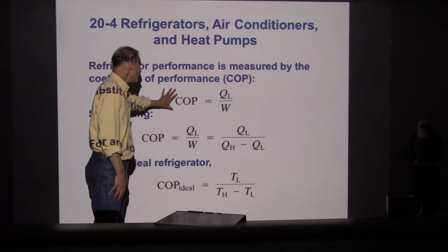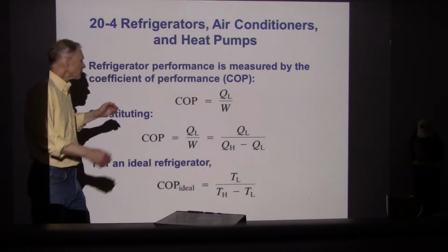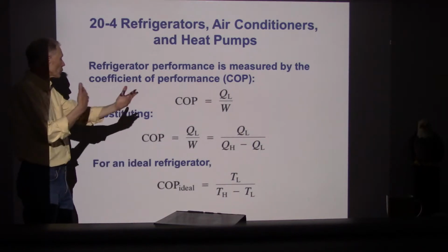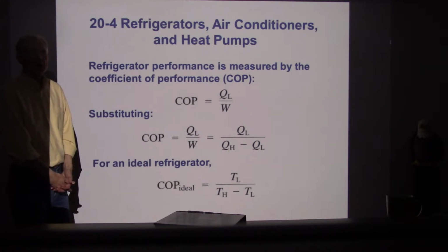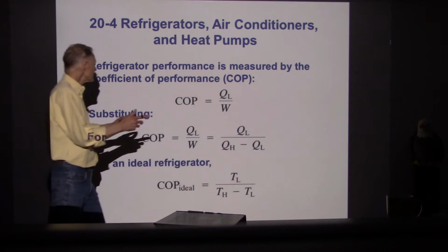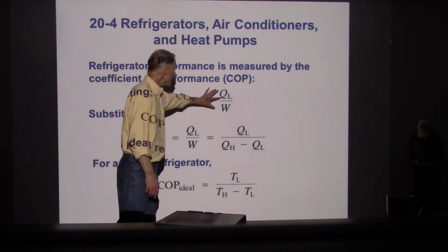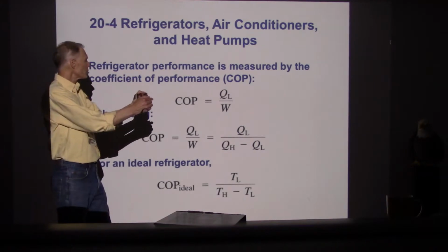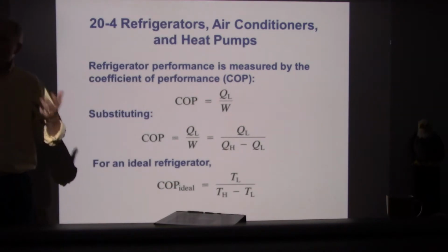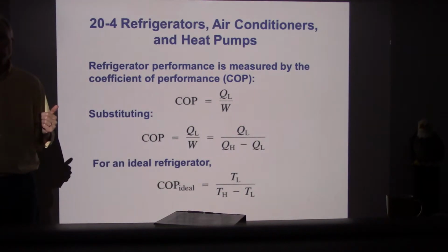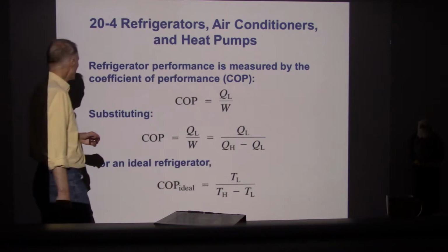So this is called the coefficient of performance, and the heat pump that I have at home right now as a heater and cooler has a coefficient of performance of about 4. So let's see what that means. The coefficient of performance is asking how much heat we can transfer divided by how much work I need to invest. Remember, with a heat pump, I'm not getting work out, I'm putting work in. Specifically, the work I put in is operating an electric motor to operate the compressor. Remember, we have to have a compressor to make this heat pump work.